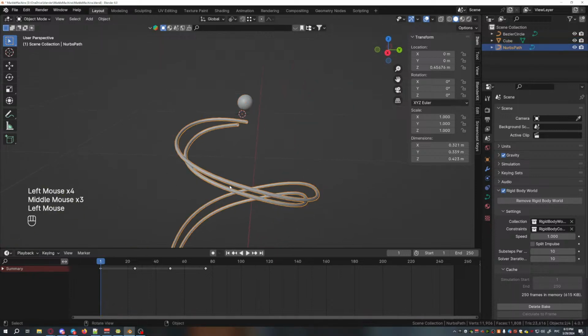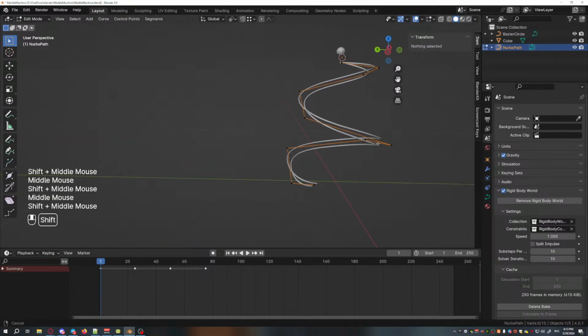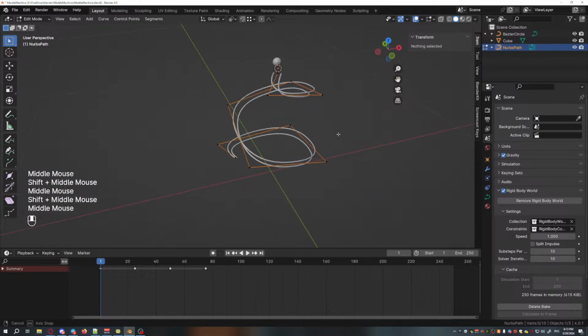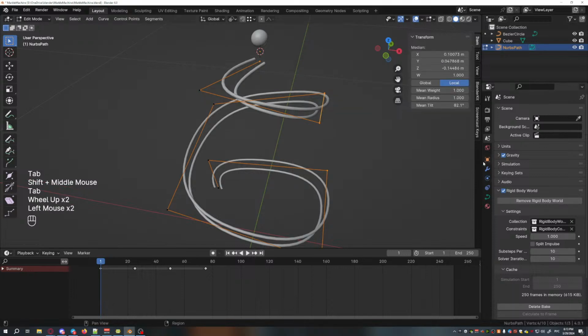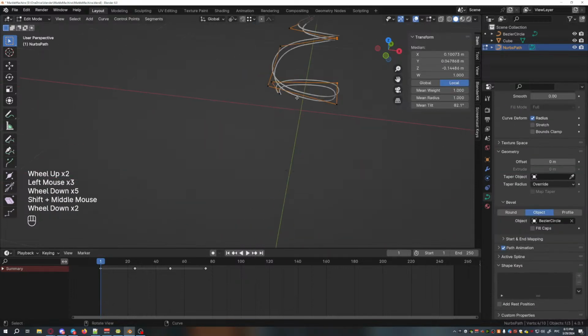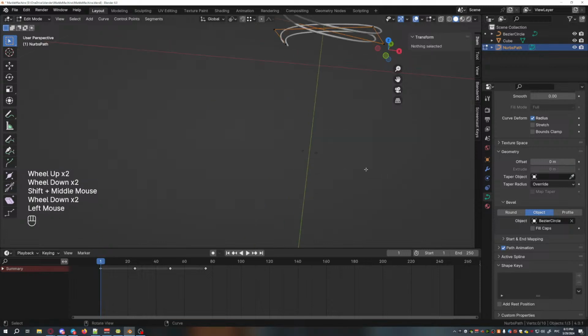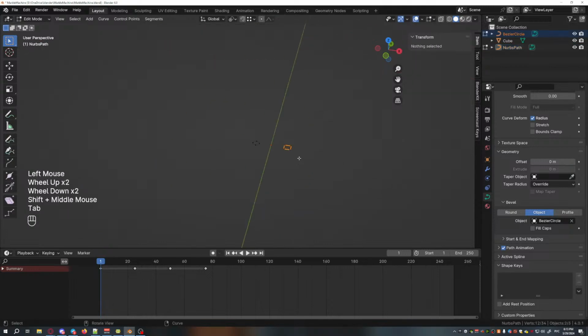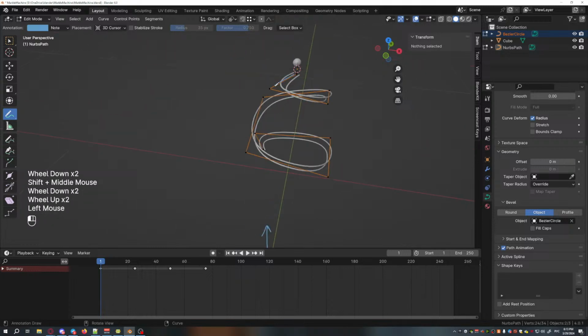All right. So so far I just sketched out the path for the railings on my marble machine. Then for this curve, I selected the object through which it was beveled. So basically, these two circles were taken as basic geometry and extruded upwards along the entire length of this path.